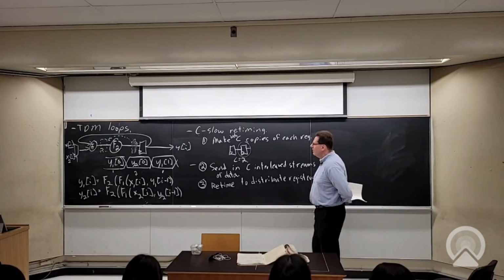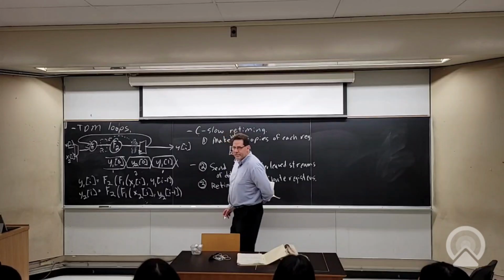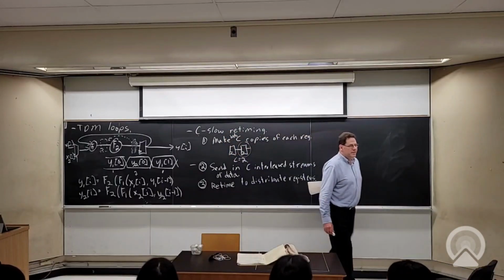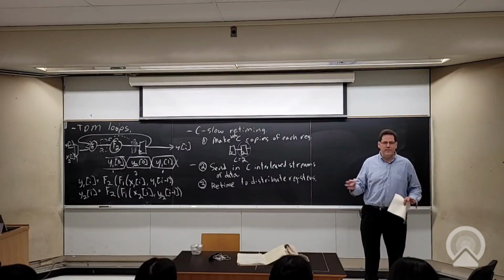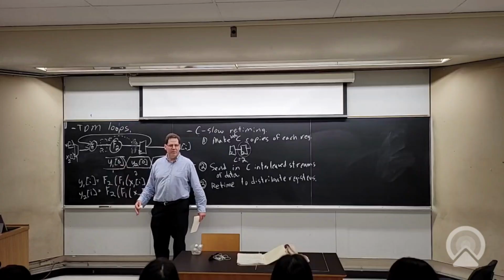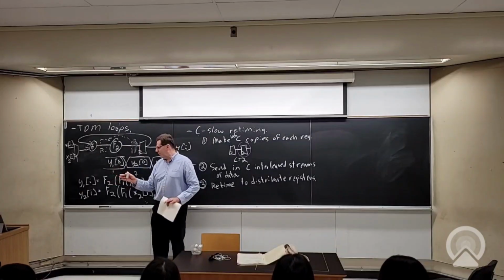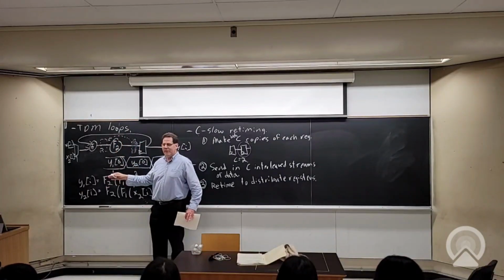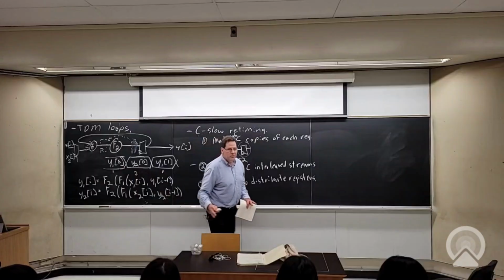Could I duplicate my loop, one for each stream? You could do that, yeah. And then just enable every other cycle. Yeah, and that's another technique people could use. So let's say this was limiting the speed of my system. I've got some data path that runs really fast, but I also need this, and it's got this annoying loop in it. You could make many copies of it, and then if the rest of your hardware is faster, at the output of your 2 copies you could multiplex them together in time and send them into your faster hardware.